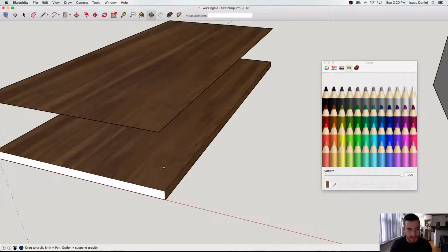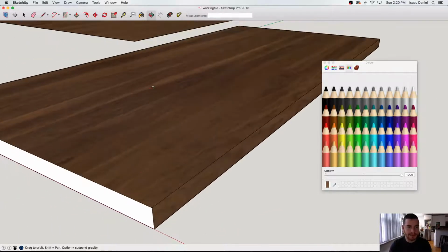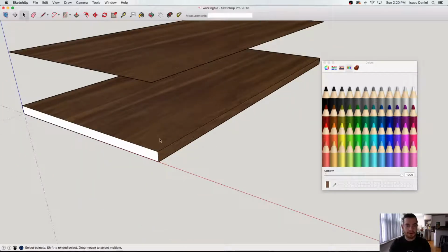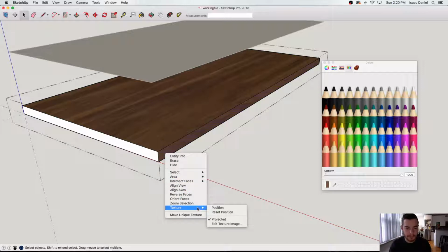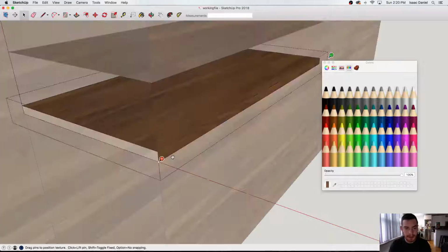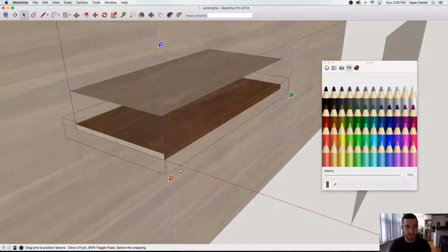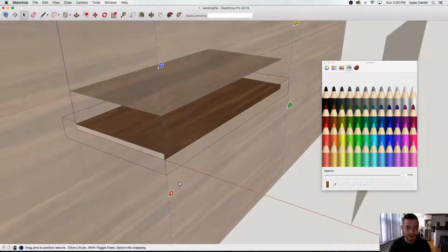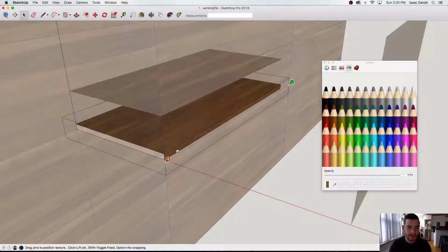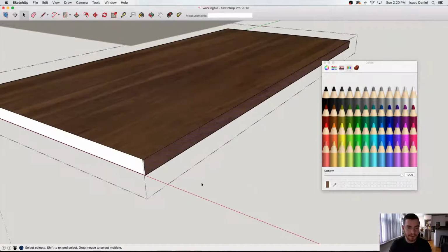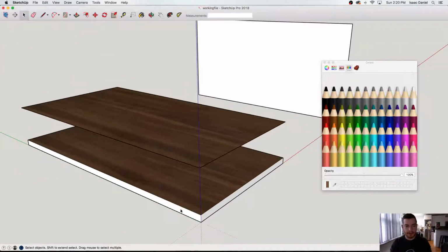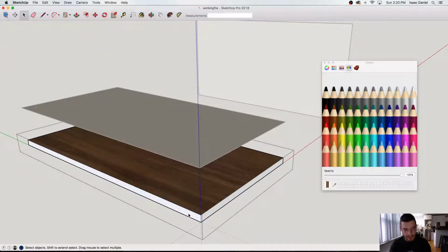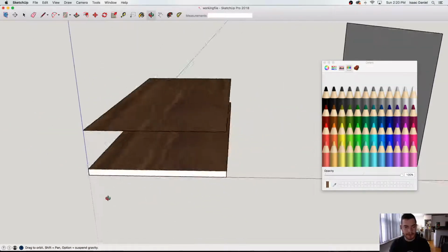If these don't line up nicely, like maybe you found a sappy section of the panel, you can always move it by going to that actual rectangle and positioning it. You can move this up or down so that it matches better. For our application, it actually matched pretty well, so we're fine there. And then we can do the same other side now that we have that there, and we'll just paste that there as well. So now we have 4 sides of this.